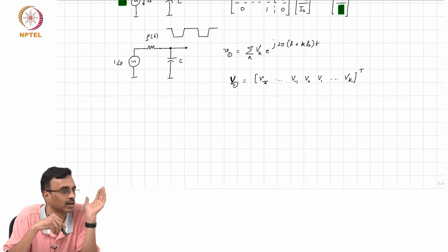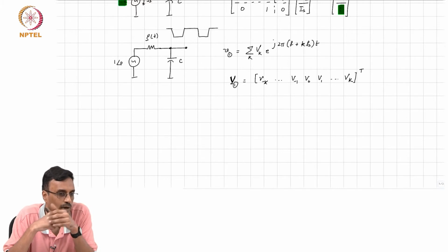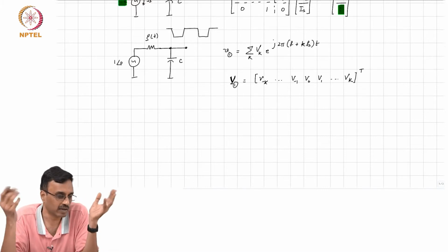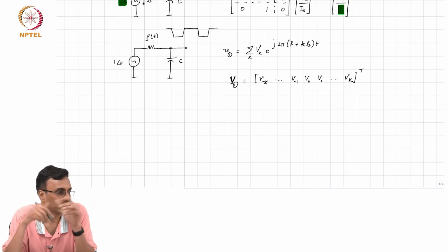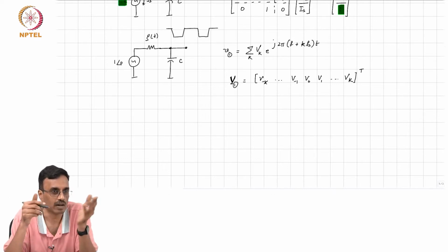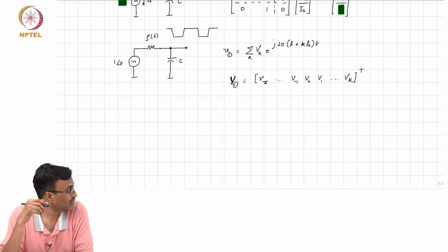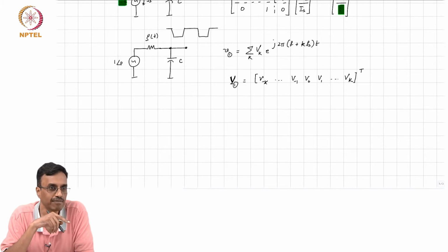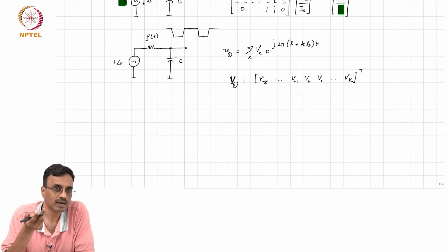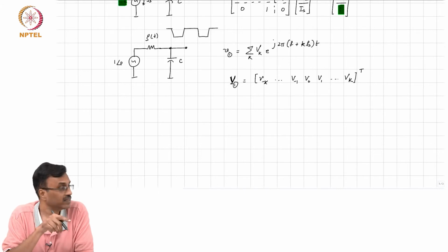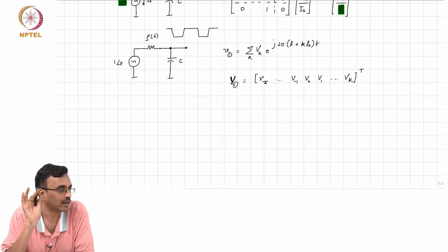The network is varying with time, and it seems reasonable that to capture its behavior you need, within quotes, to work a lot harder. Fortunately for us, KCL and KVL must be satisfied not merely at a frequency f, but at every frequency of the form f plus k times fs.